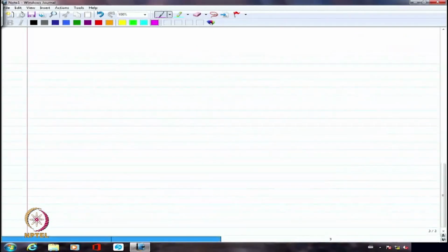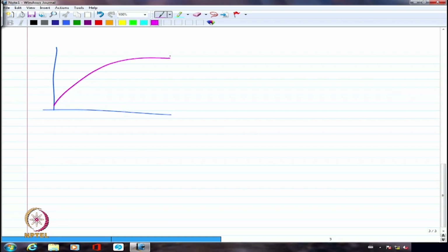So now let us try to look at again the external characteristics briefly. So if I am going to have actually this as the OCC, right? This is EG and this is going to be my IFS, or I would say this is also incidentally IA later on when I am going to connect it really as a series generator.